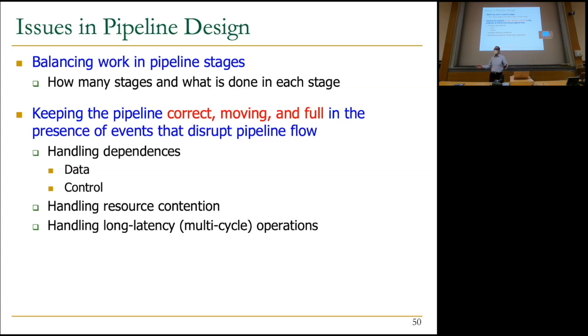We're going to assume in the rest of this lecture that memory takes one cycle, but always keep in mind that memory doesn't take one cycle. If it takes 10 cycles, 100 cycles, the pipeline needs to stop, right? You need to wait for memory. So what do you do in that case? Your throughput actually reduces drastically whenever you need to go to memory, if it doesn't take one cycle.